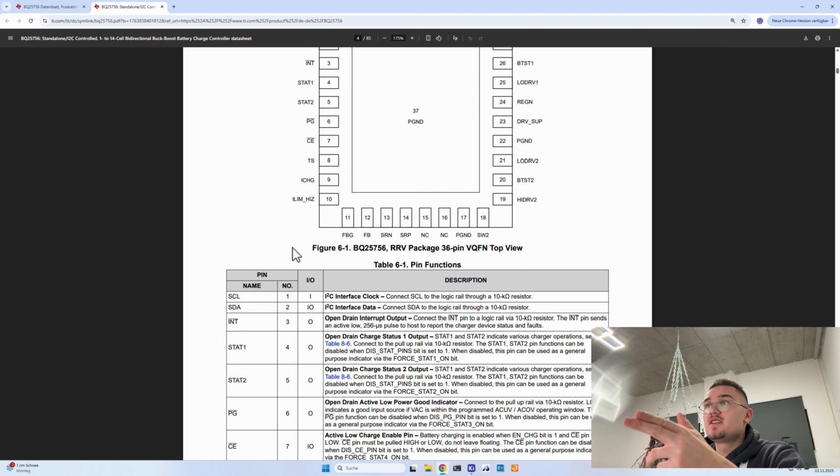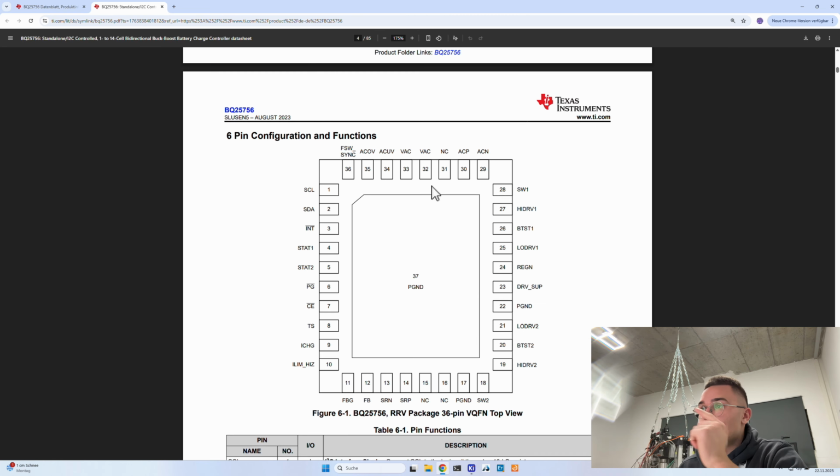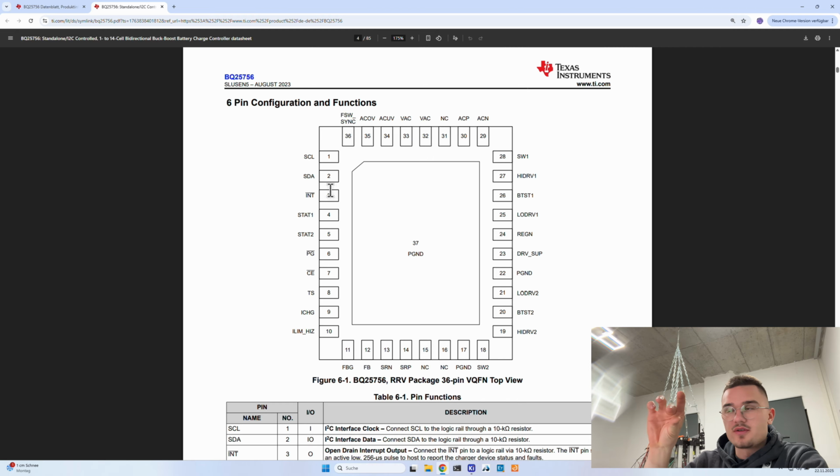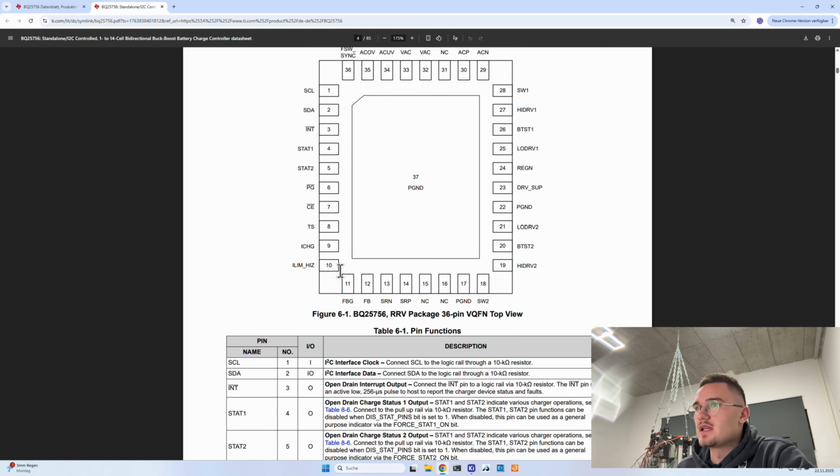And then you can see here the numeration of the pins. That will be important for the PCB itself. So you place the chip on the PCB, or you make a footprint for it. We call the footprint the place where this chip goes on the PCB. We need to know the numeration of the pins, where pin 1 is, and what function it has, to draw the circuit correctly. Exactly.